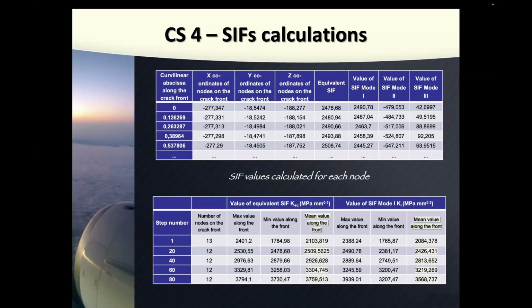So in another presentation, which I have here, but unfortunately it's on my laptop, I had an example of that. They find very long cracks and they weld them. You take a welding machine and weld the crack. After a couple of months, the crack is on the same spot near the weld. It's misguiding the crack front. Yes, like in a glass: if there's a crack and then we scratch in front, then it doesn't go further. So I also have these images.